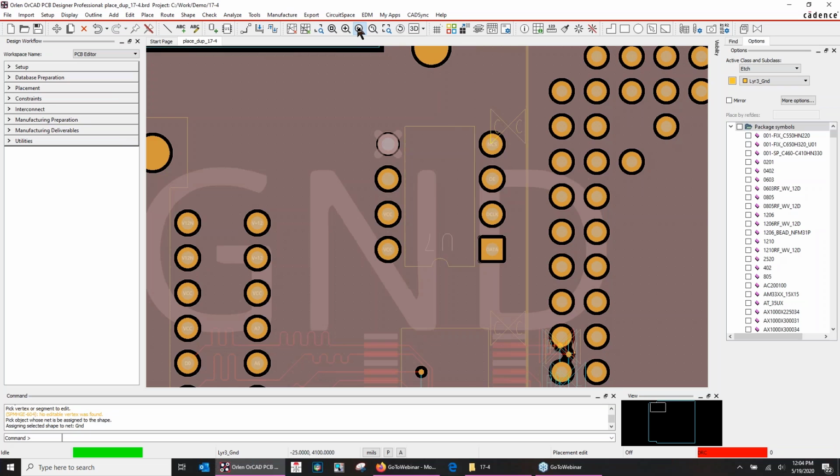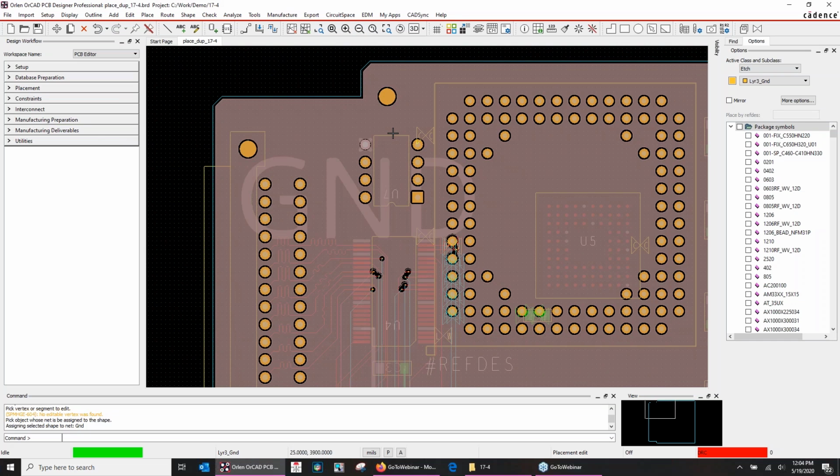And there's my ground. I can Z copy then again for the power, and I can actually pull it back further back from the ground, making the board itself like a capacitor, having the power and ground, two different shapes. I can pull that back. And I've done that on some boards. Basically, think about it. You're building a capacitor with your power and ground planes in there, pulling it back a little bit more and build this overall capacitor across the entire board.